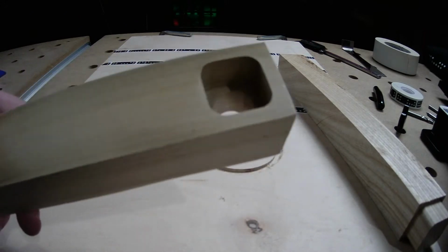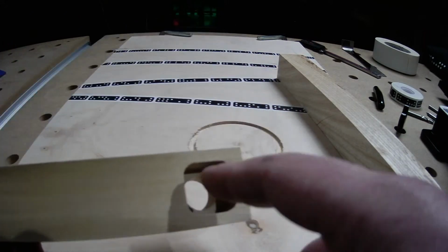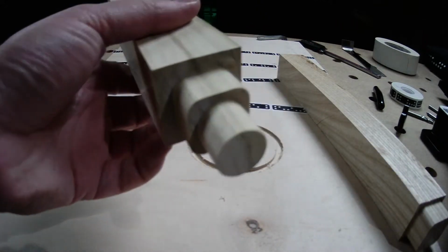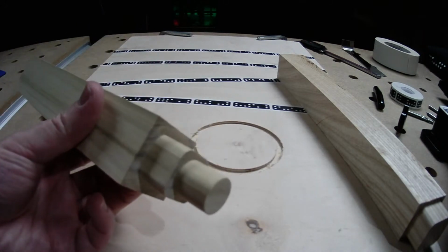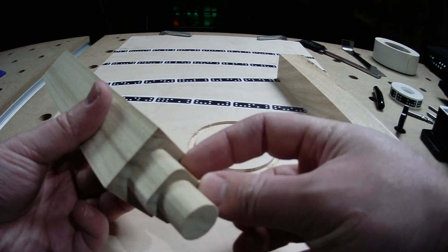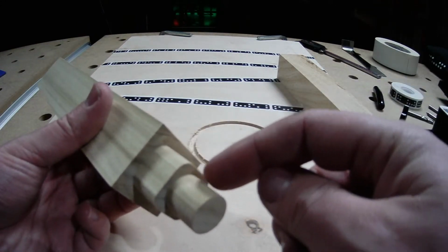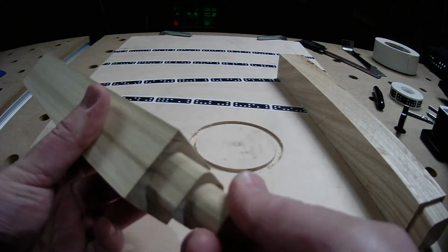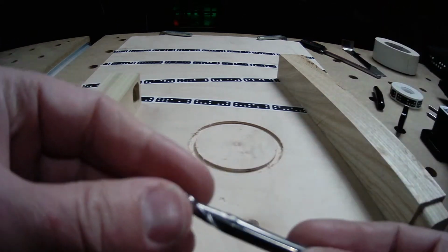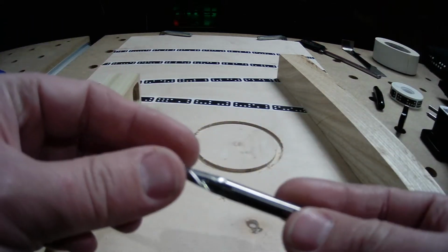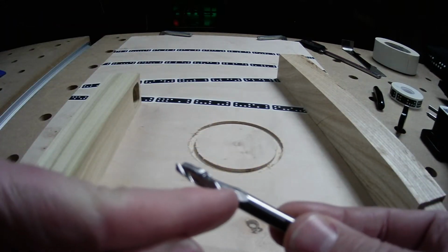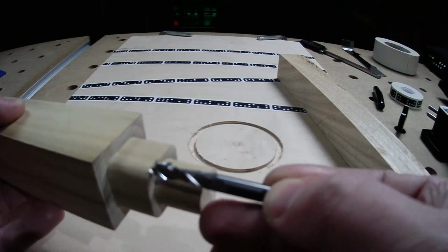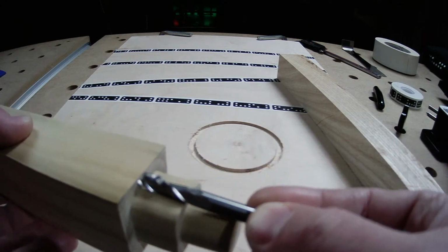This is a fun one where you see a circular through tenon, but you have the alignment of a square. And this is a fun cheat because you can cut this tenon with the standard Origin bit, because each of these is only 3/4 inch deep. And because you're stepping off after 3/4 inch, you're not going to end up rubbing against the material. That's the deal with these bits, that it stops cutting at 3/4 inch. But if you move it out, then it's not going to be rubbing up against that. It's going to be cutting another 3/4 of an inch.